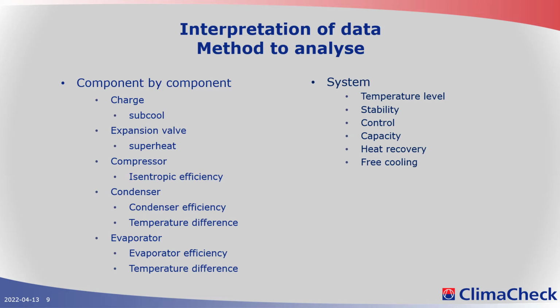It's strange when you're running an air conditioning system to produce 10-degree chilled water when it's 5 degrees outside, where you could actually cool with the outdoor air. We should not waste energy when we don't need to.